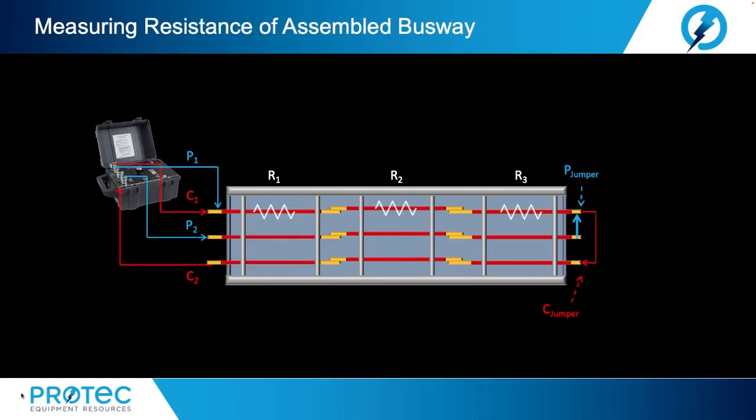So effectively in this configuration, I am only measuring the voltage drop from the P1 to the 3rd section of the bus bar, or where the jumper is placed at the end of segment 3. And now I can take a very accurate measurement of just the A bus and all of the through-bolt connections.